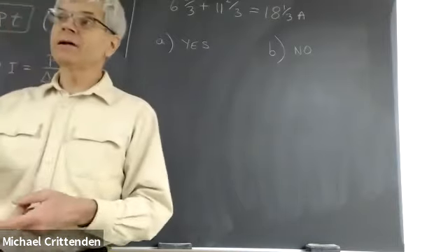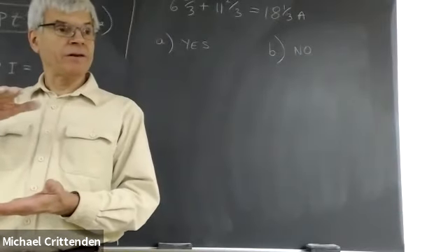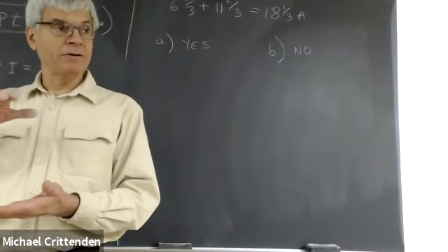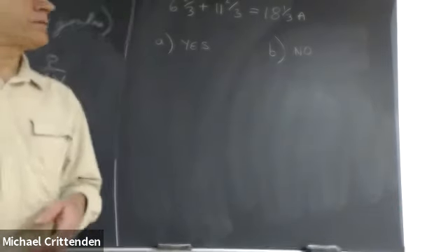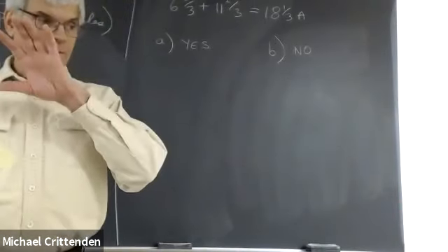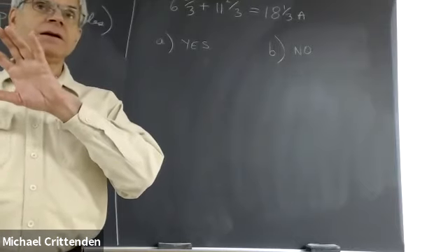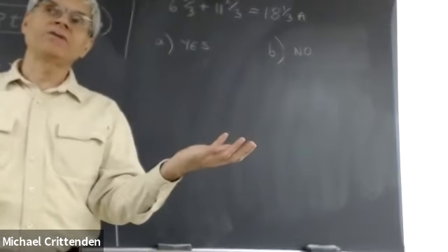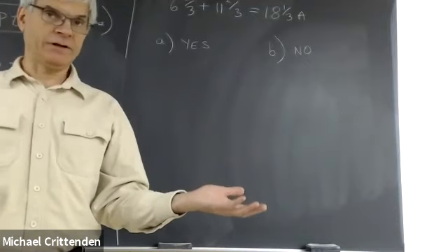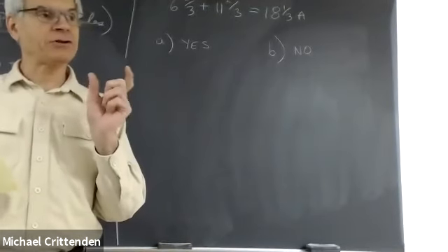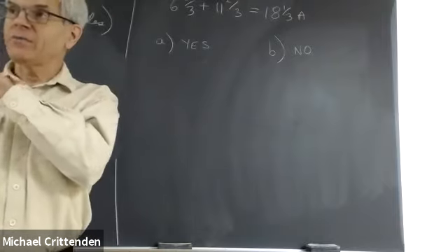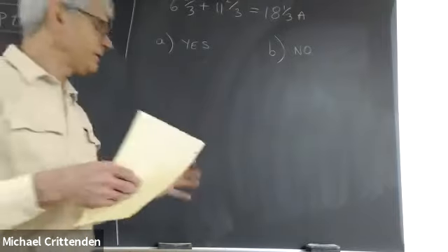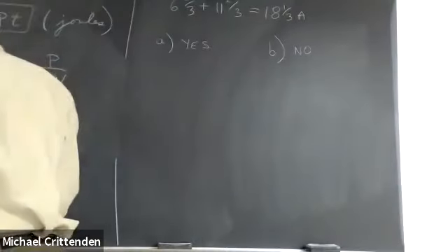You put that kind of load on a pile of calculator batteries, even if they're brand new, the voltage just drops to practically 0. And so the EMF is, I guess one way of saying it would be the unloaded voltage. How many volts are actually being created in there without the I times R loss that you get when you draw current on it.